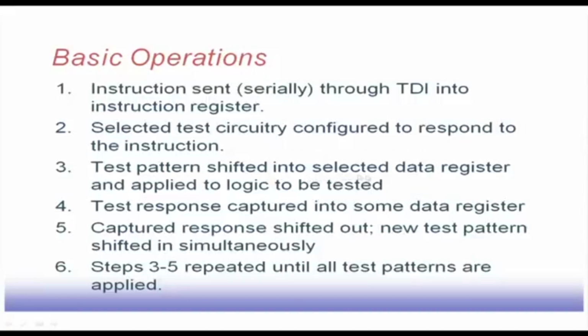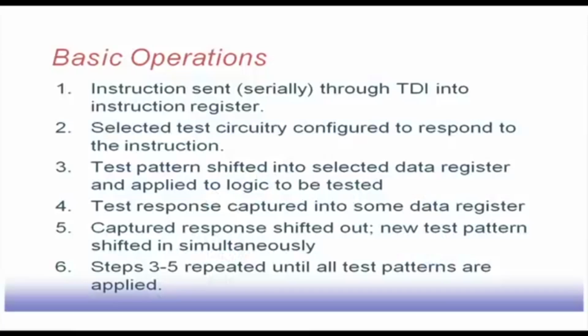Then the test pattern is shifted into the selected data register and applied to the logic to be tested. If the command is to shift in some test pattern through the boundary scan cells into the boundary scan register, then it can do some shift operation over a number of cycles. If the instruction is to start a BIST operation, then it will start a BIST operation. It may be to capture some response, so it will capture the response. There are various instructions.